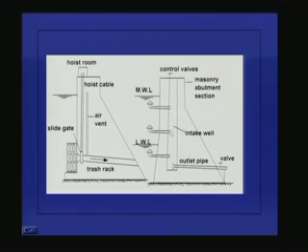So this intake well is always full of water, so it is a wet intake. Water is entering through these inlet pipes into this intake well, and the outlet pipe goes from this intake well, and the flow in the outlet pipe itself can be controlled through the valve, and flow into the intake well can also be controlled through these control valves, and this is basically the masonry abutment section. So for taking water out of a reservoir behind a gravity dam, either I can follow this particular arrangement for intake or this particular arrangement.